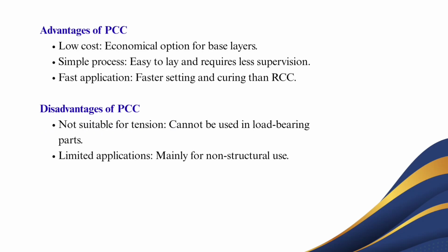Then there are the advantages of PCC. PCC is low in cost, so it provides an economical option for base layers. Simple process. PCC is easy to lay and requires less supervision. It is fast in application because the setting and curing of the PCC is faster as compared to the RCC. So there are some disadvantages of PCC, like it is not suitable for tension.